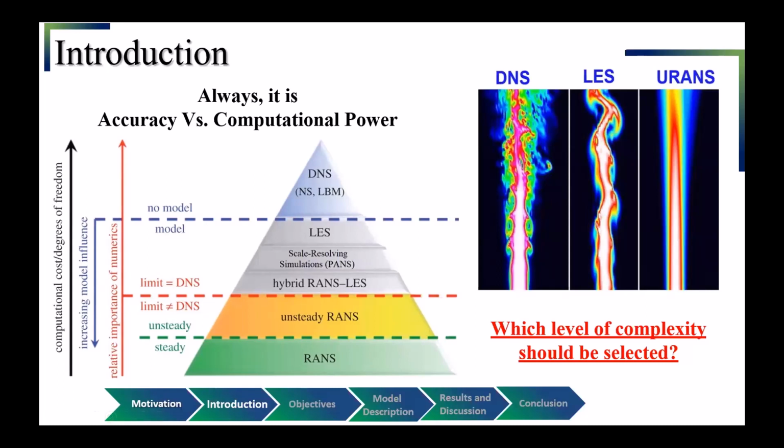Okay, so talking about turbulence modeling, the RANS methodology is computationally efficient but limited in capturing the full range of flow physics, coherent turbulence, because it's a one-point closure approach. DNS and LES techniques provide accurate computations but may be computationally overwhelming for applications in aerospace and ocean engineering.